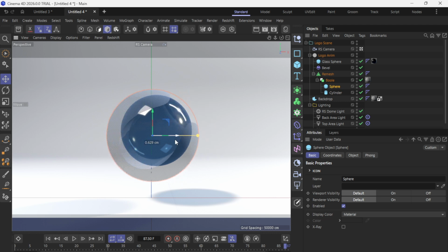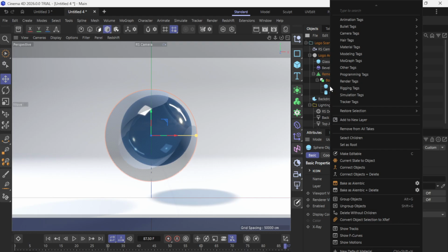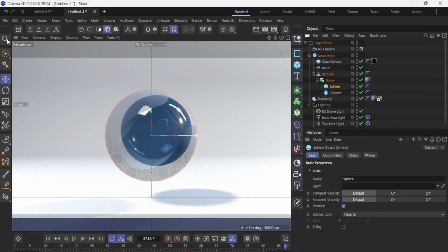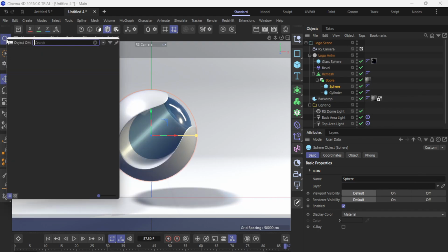To control how fast it spins, increase the speed parameter in the motor tag. Higher values give you a faster continuous rotation. If you need a bit of push at the start, say your object feels heavy at rest, use torque to give it that initial kick. Think of speed as the target pace and torque as the muscle that helps it get going. Play the timeline to see the rotation in action and adjust speed and torque until it feels right. If you want the opposite direction, simply use a negative speed value.